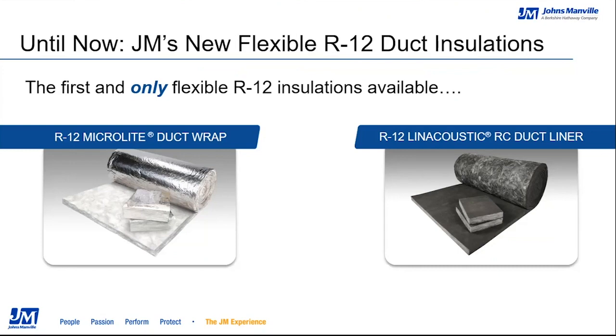The second product, our LINACOUSTIC RC duct liner, this is a 3-inch product that we came out with to the market. We're seeing a good uptick in sales on this product. This product is also readily available. Remember when I indicated the NRC at 1 is pretty much perfect absorption. The NRC on this product is 1.05. Johns Manville offers multiple liner SKUs with this product in different widths, and that's important because sheet metal shops have different connections and different setups and different applications that they manufacture, and we offer every width for those solutions.